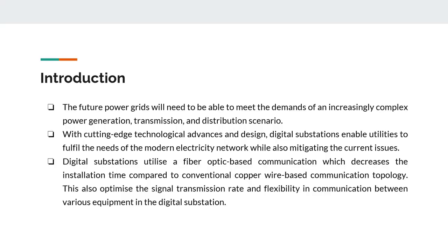The future power grid will need to be able to meet the demands of an increasingly complex power generation, transmission, and distribution scenario. With cutting-edge technological advances and design, digital substations enable utilities to fulfill the needs of the modern electricity network while also mitigating current issues. Digital substations utilize fiber optic-based communication, which decreases the installation time compared to conventional copper wire-based communication topology. This also optimizes the signal transmission rate and flexibility in communication between various equipment in the digital substation.